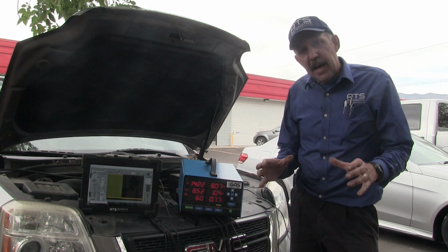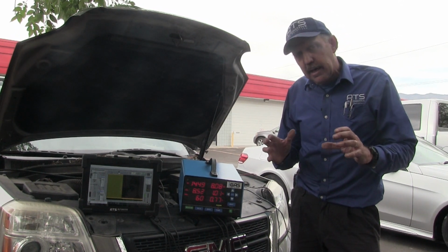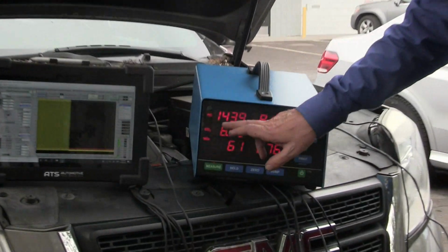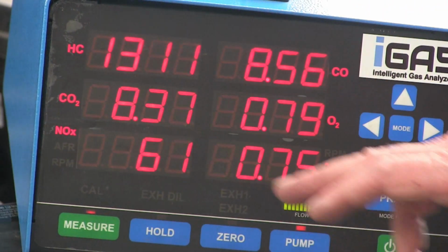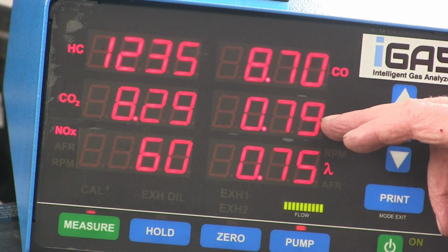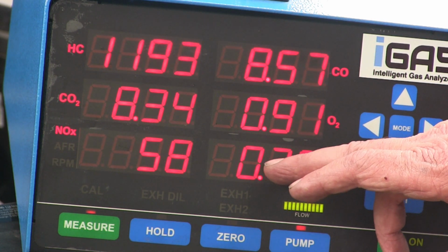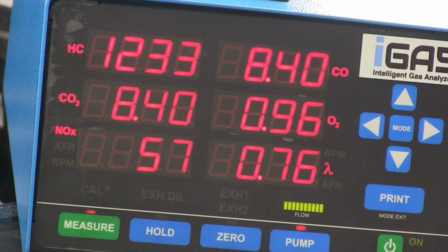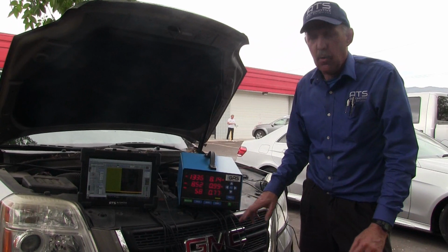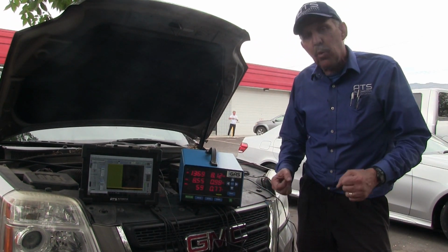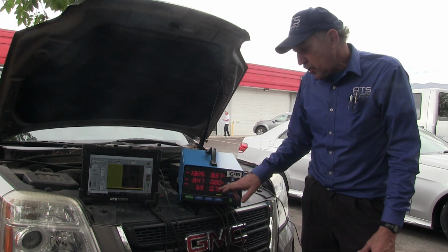Now that we've got a 5 gas analyzer connected to this vehicle, what I'm interested in looking at is the gas basis. When we look at this, we have a lot of HC. The CO is way high, CO2 is way low. The oxygen is about right, but the oxygen is right because I am way rich. 0.76, that's 24% too rich. This should be 1.0. That would be a lambda of 1, which means that I'm stoichiometric. Now this is not stoich, this is way rich.